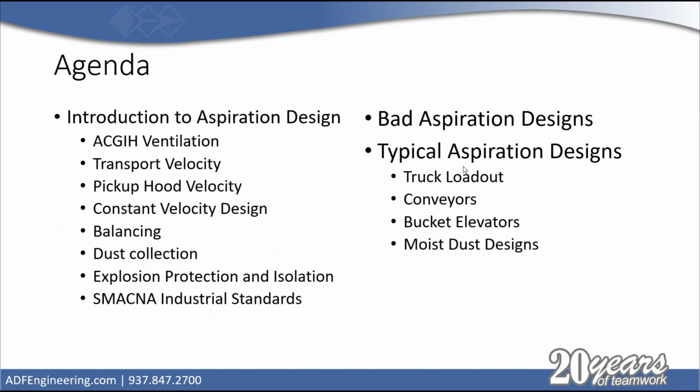So just a quick agenda. We're going to start with essentially dust aspiration design 101, introduction to aspiration design, ACGIH, what that is. We'll go through what transport velocity, pickup hood velocity, and constant velocity design approach. We'll talk about balancing a little bit and the importance of that.